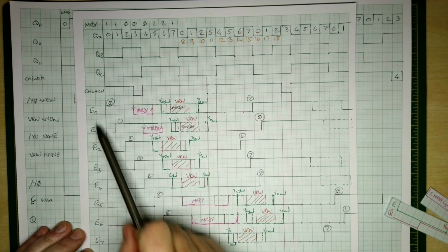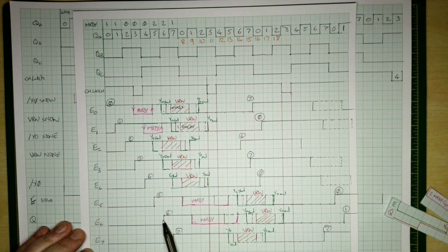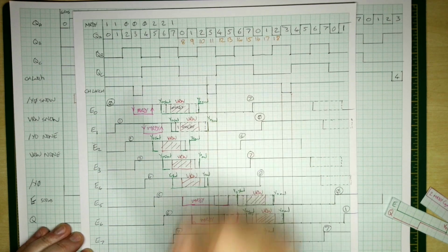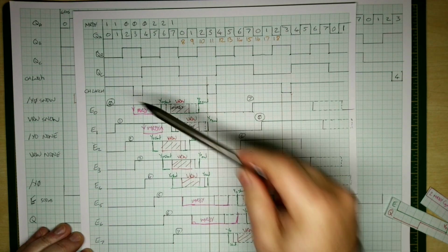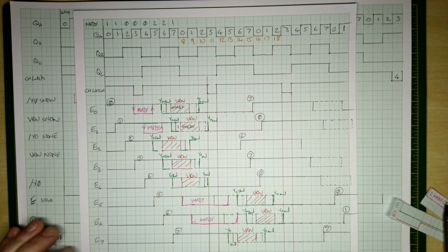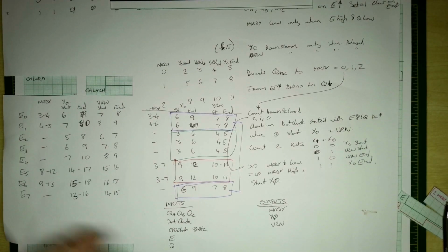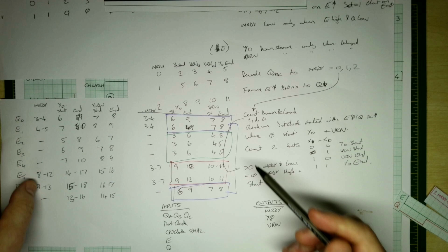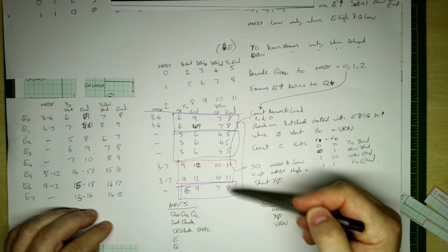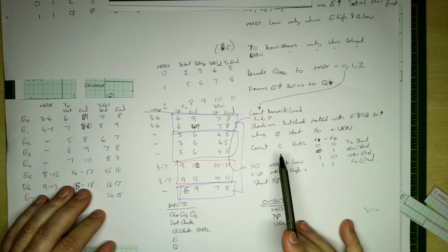So what I've then done down here is actually worked through all these various relative starting points of the E clock signal, starting on this point in the CRTC cycle. And what this has allowed me to do is to produce a sort of table of the values relative to this starting point. And what it turns out to, this is a bit of a messy diagram, but it probably can indicate that for the various E starting points, there are three groups of data